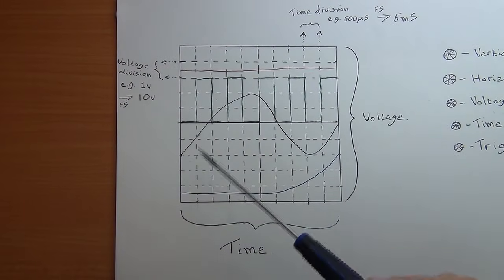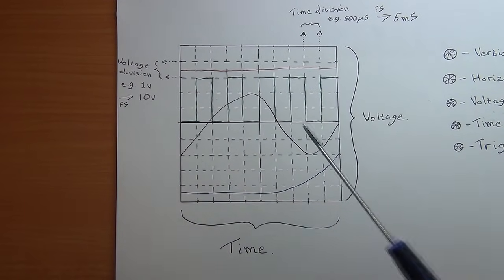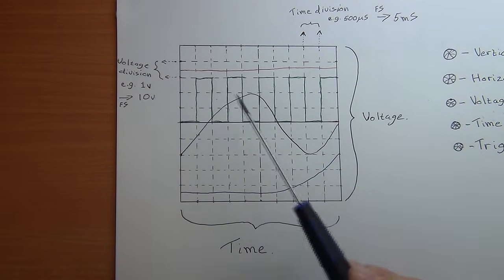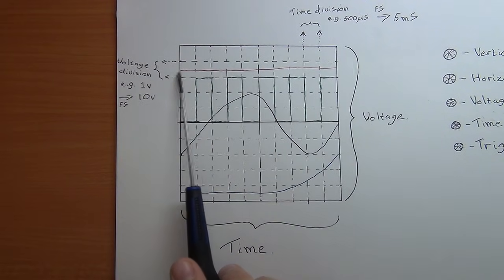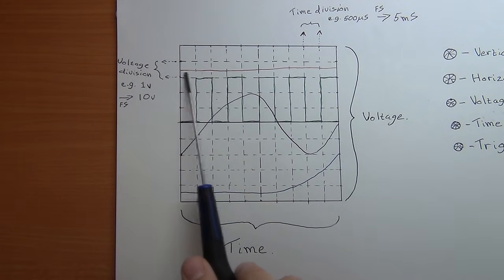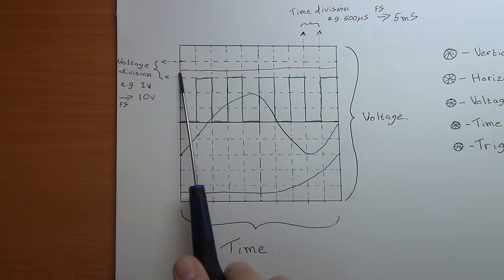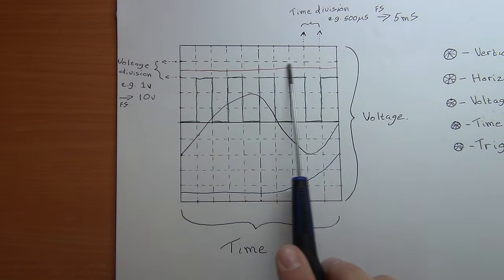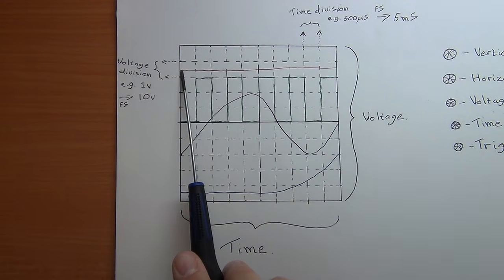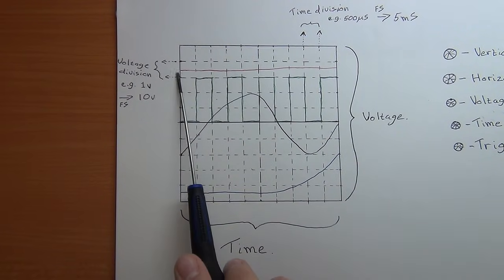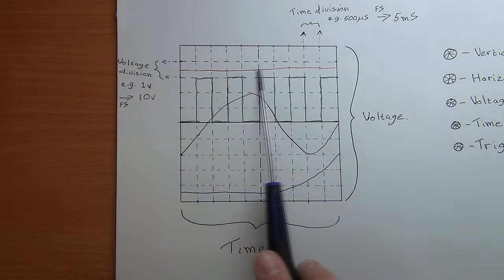So now let's have a look at potentially the types of signals which you can have coming in on your oscilloscope, and how potentially they would be represented. And of course, there are thousands of types of signals that you can get to view, but let's have a look at a few. Now, the one I wanted to point out was something which a digital multimeter can represent very nicely, a signal at a certain voltage level that stays the same. And on an oscilloscope, that's still a signal, but it's going to be represented by a straight line, as this red line represents here. So your level stays the same, it's not changing over time.